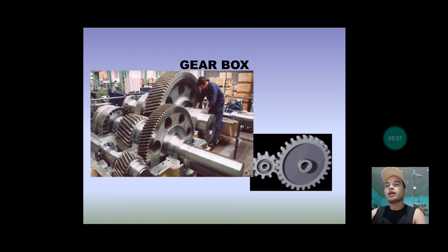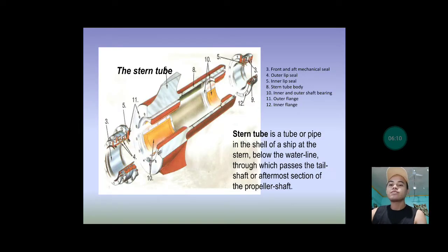So you need a gearbox. While if you have a main engine and you want to connect a shaft generator, maybe you have to use a gearbox, and depending on the speed, you can increase the speed using a gearbox. Since the gearbox has metal to metal components inside, gearbox lubrication is very important for this kind of equipment on board ship.